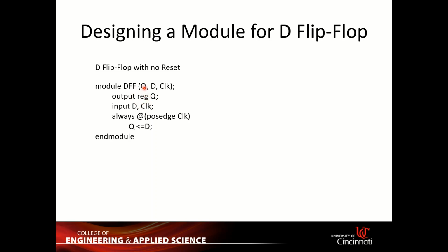The reason you need to write down this reg keyword right here is because you are using behavioral modeling. In this case we will design a positive edge clock, so you can write down posedge clock.